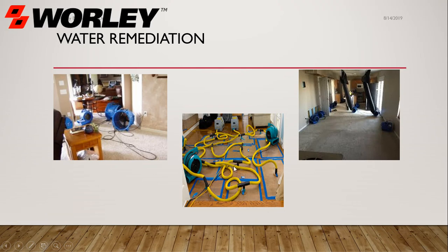We've got some specific drying here. So we've got a hardwood floor that we're trying to dry out. We've got blowers moving air into these jackets. These jackets are pulling up the air, and they are going into a dehumidifier. This is a top-down water loss where you've got blowers blowing up into the cavity, trying to move the air. You've got these blowers set up so they're in a circular rotation. Again, moving that air around, not just blowing it straight on the surface.